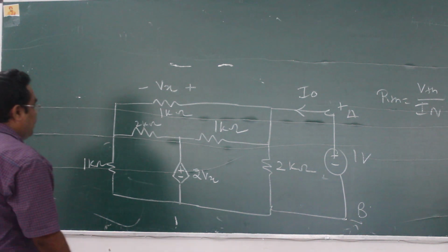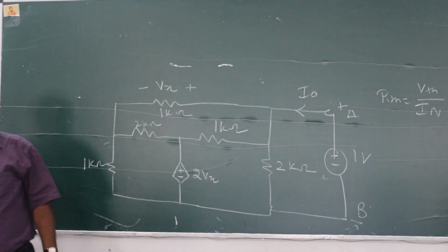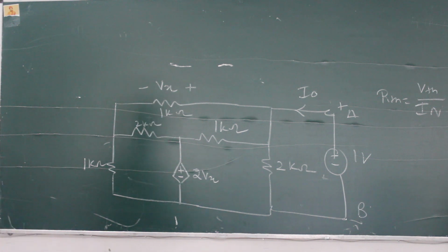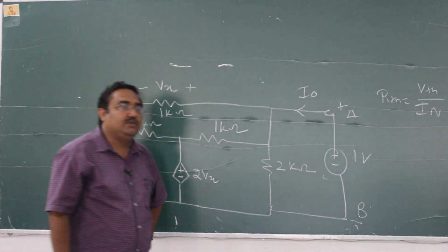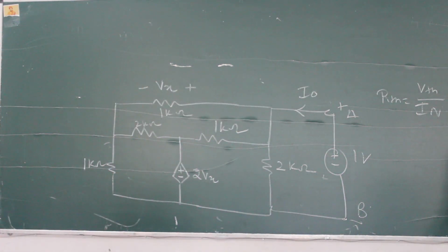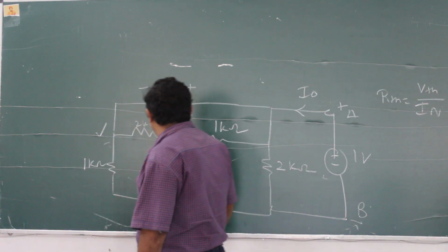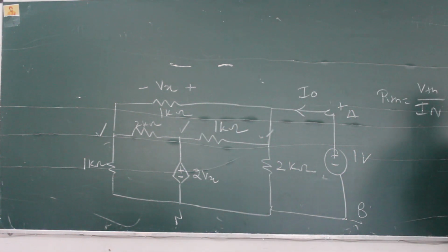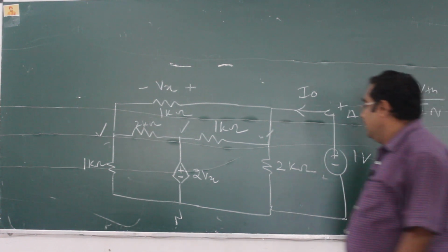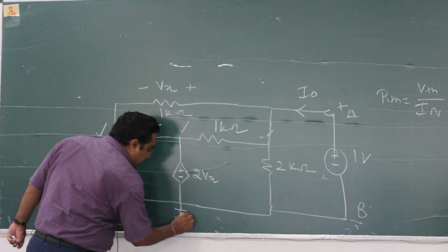So now I can apply any law which is comfortable for me for solution purposes. Which law that you have studied so far will be more comfortable in this problem? I think so, nodal analysis. Do you agree? So how many nodes are you seeing here? How many nodes? 4. Everybody agrees? There are 4 nodes. Let us check it. 1, 2, 3 and 4. Do you agree? Okay, 4 nodes are there, out of which one has to be made a ground. So let us make the bottom node the ground node.